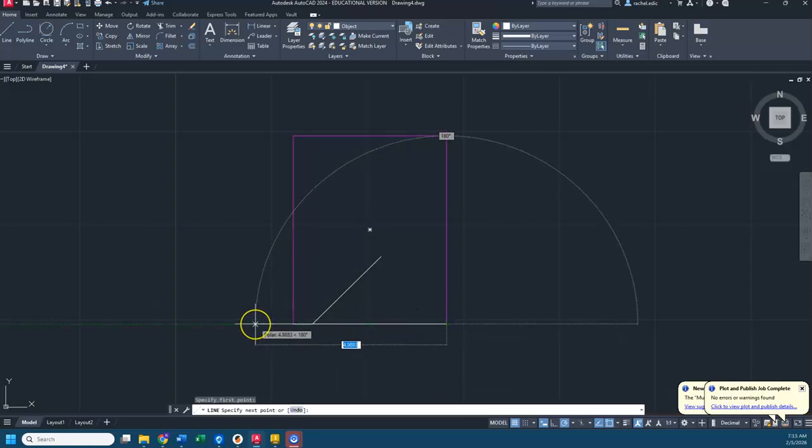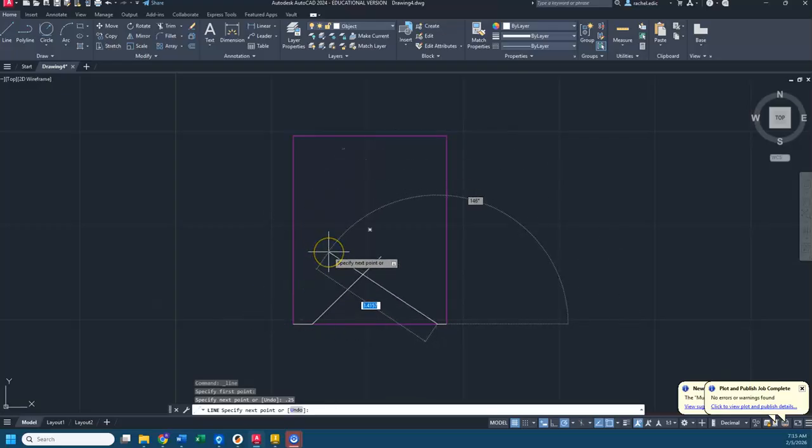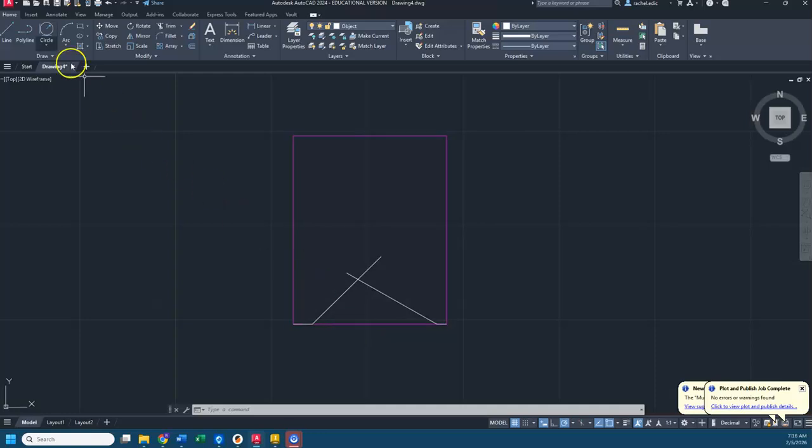So I'm going to come over to the left, 0.25, and I'm going to go up at a 30-degree angle. But remember, it's saying pulling from here up is 30 degrees. If this is 180, I'm going to need to go the opposite of that, so 150. So I'm going to press tab, 150, tab, and I'm just going to click. What I needed to know is kind of this information of what's happening down here, except there's a horizontal here, and that's going to be offset from the bottom here.